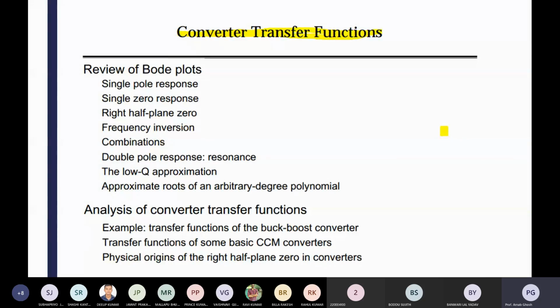I am telling you that on the input side, plus minus 50% is actually not possible. In most cases you can say plus minus 10% of input side variations. If you are designing your converter up to plus minus 50%, then your converter is very good. In output voltage you can do the same thing, plus minus 50%. You can suddenly reduce the load resistance, which may cause additional current in the system. Additional current means power should be constant, so voltage will go down. So you can do load variations.